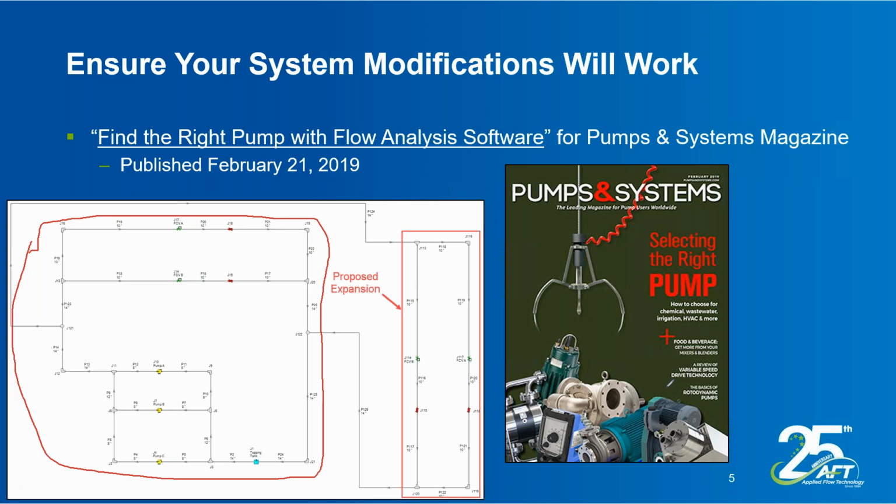And sure enough, when they turned on the flows to the new heat exchangers, they didn't receive any flow at all because the pumps were already maxed out, serving the demands for the rest of the system. So the moral of the story is it's really important to do a flow analysis so that you can make sure that your system and your design will actually work.